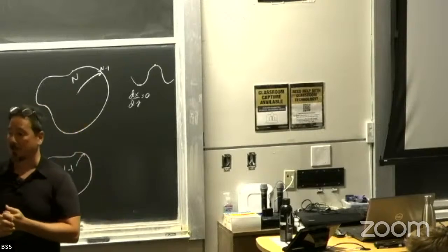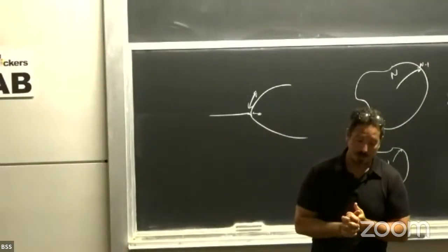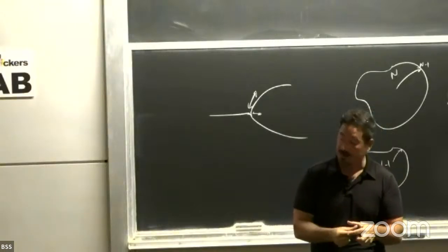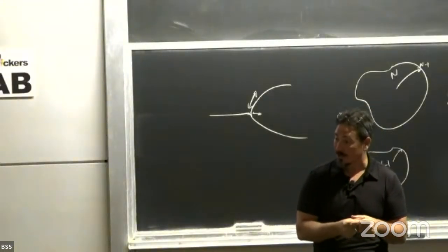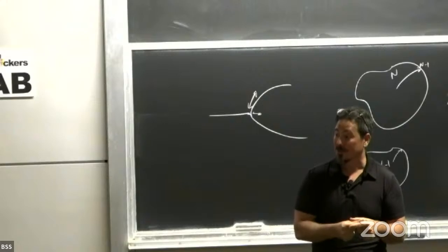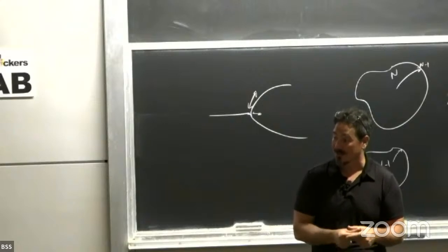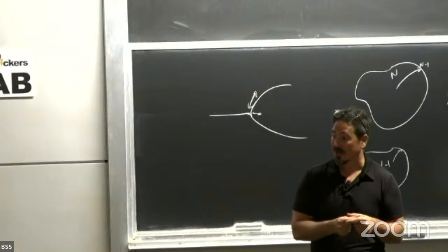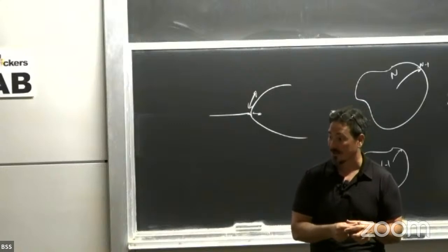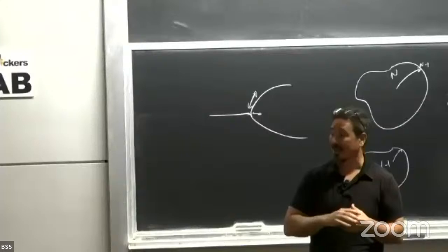Yeah, so are you asking about the little nanoscopic domains, the magnets? We build those using e-beam lithography. That's not available in all clean rooms. But we are developing a method to use phase plates to allow us to do it with just photolithography, and that is available everywhere.